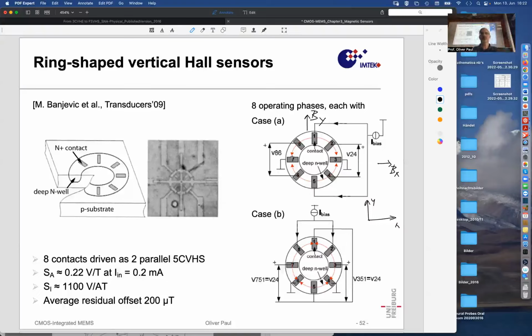And you can then invert the measurement philosophy. You can do the 4-fold switching, cyclically replacing contacts, and that leads to another biasing, as you see it here, with the voltages now measured between what was previously the current contacts, and the previous voltage contacts now being the current contacts.